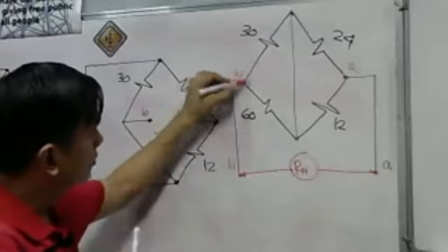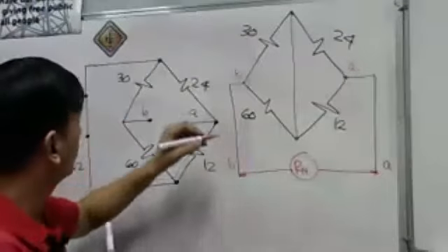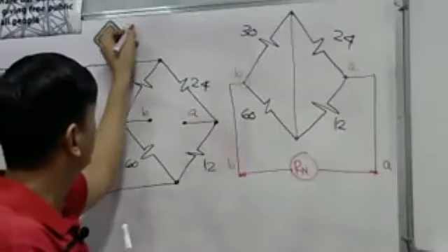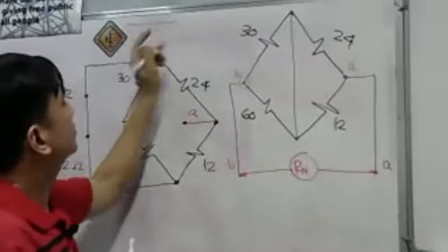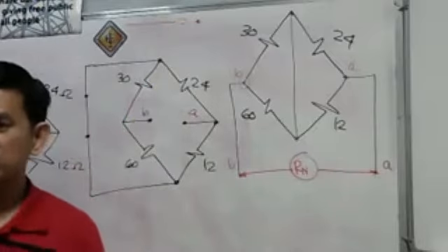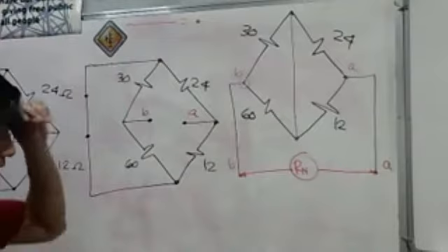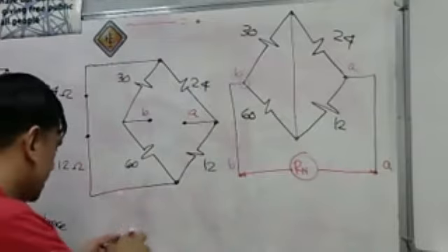This is one common node, and this short-circuiting conductor is just a common node. Always remember, if we have a conductor here, that is just equivalent to a dot. Always remember that. Now, I will redraw the circuit. This will be the figure now.